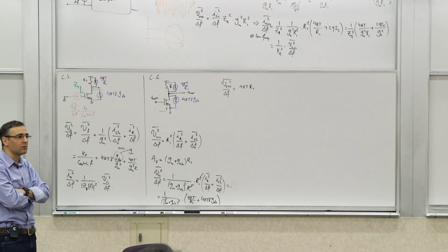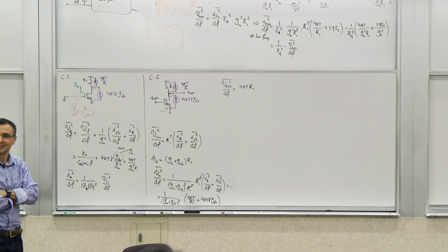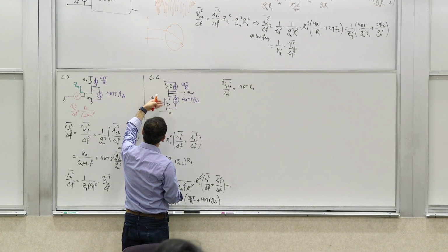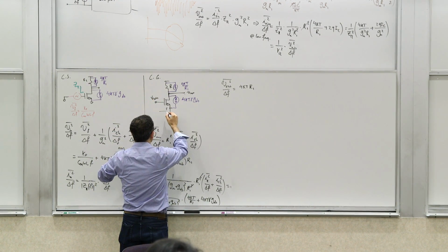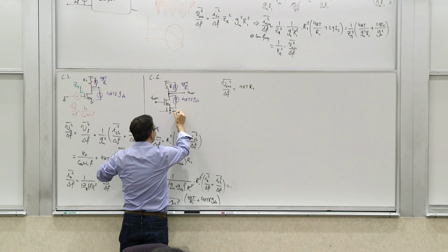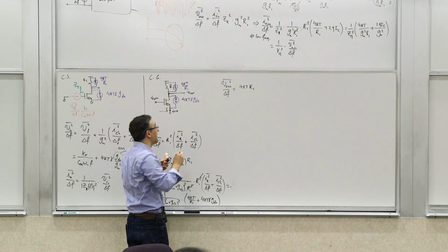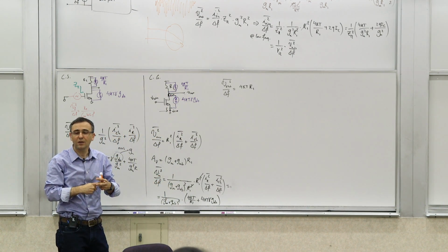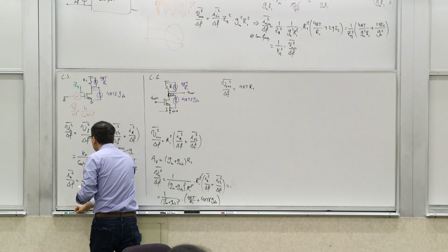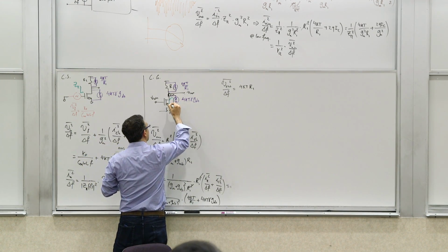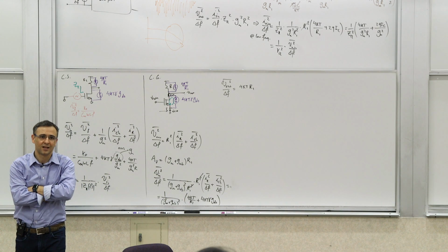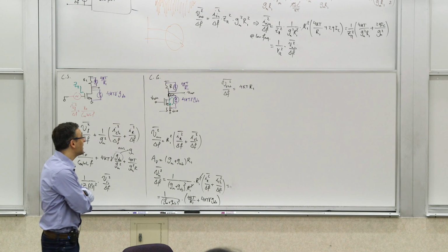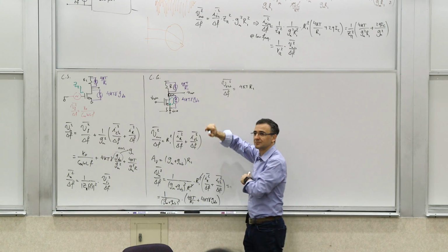Would that noise go into the R1? Can it? No, because if you think about it, this is not connected really if this is open circuit from that perspective, from the low frequency perspective. This current is 0. Therefore, this current has to be 0. So all of this noise current actually circulates inside the transistor. It doesn't make it to that resistor to generate noise. So all there is at the output is really this.